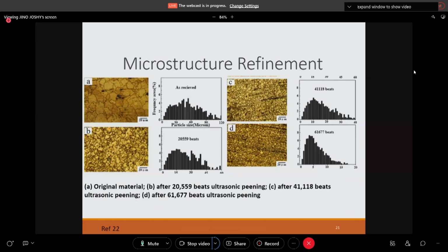They claim that due to this grain size or surface modification, a new surface is formed, and because of these new surfaces there is a possibility of a new passive layer forming on the surface, and it restricts the corrosion.